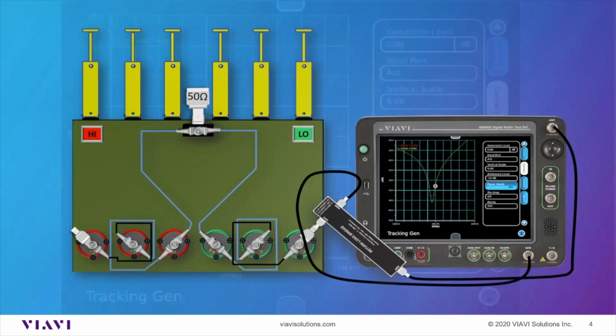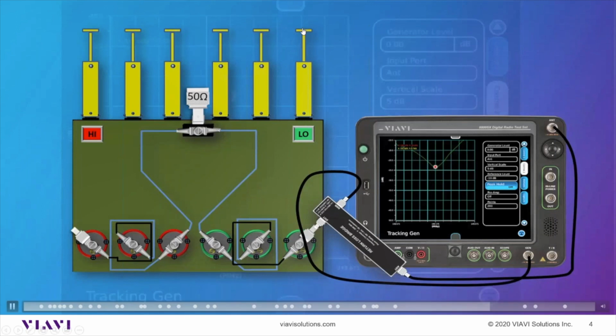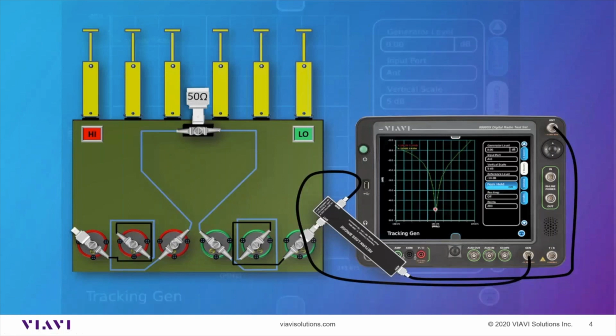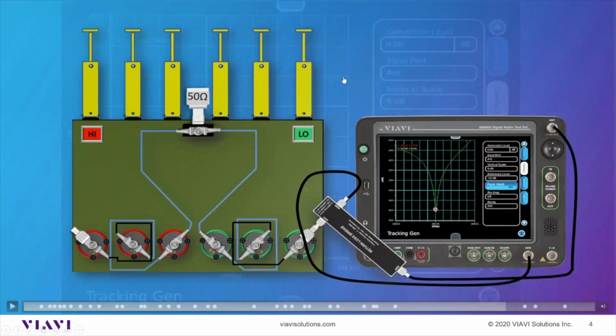So we're getting pretty close here. Like I said, you kind of go back and forth, and you kind of get the feel for this thing, so you can move these together in a sequence to get this thing to land on the sweet spot. And there it is. We're down at about -45, and this would be optimally tuned for insertion loss on the low pass side.